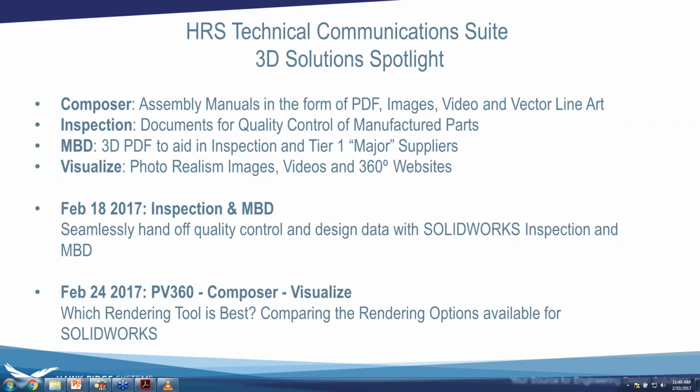and just thinking about this, if you wanted to bring that SVG back into SOLIDWORKS, it would be the same process. So yes, you can, but you just have to convert it from an SVG to a DXF, and there's a lot of free converters out there. There's also some web converters. There's some websites where they tell you to upload the file, and they send you a DXF. I've used it. I just don't trust them because I don't know what they're doing with my SVG file. But there's like a dozen free applications you can use that will actually convert it from SVG to DXF, and then you can do whatever you want with it.